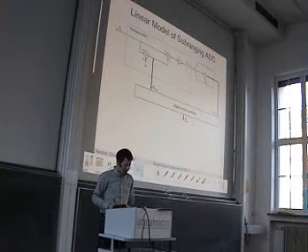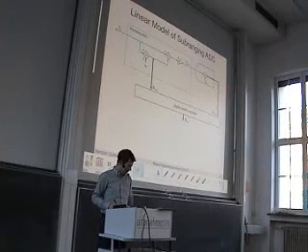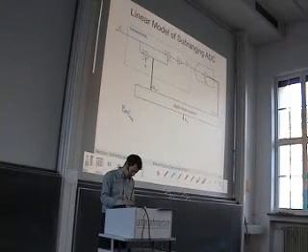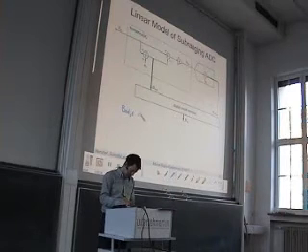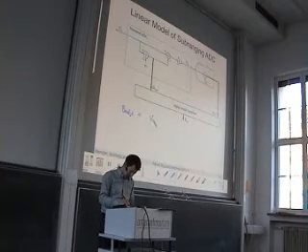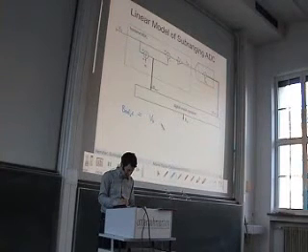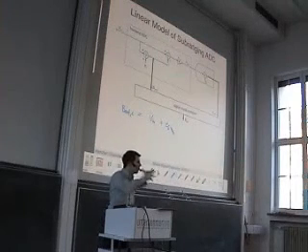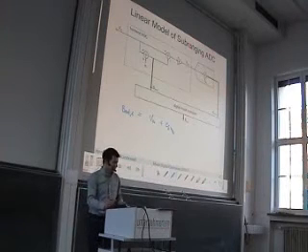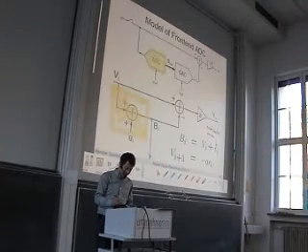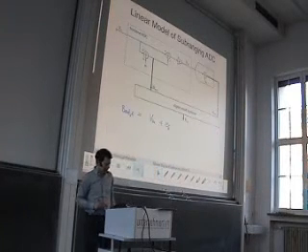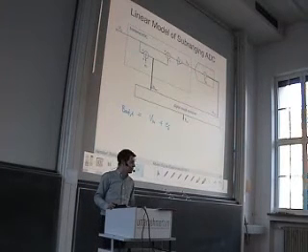Let's put it into the subranging circuit. Here we can say we have a B out 1 given by V in, exactly the formula from the last slide, plus the quantization error EF, which is the coarse quantization error from the front end ADC. So this is exactly this formula, okay? This one. And then we can do the same thing for the back end ADC.